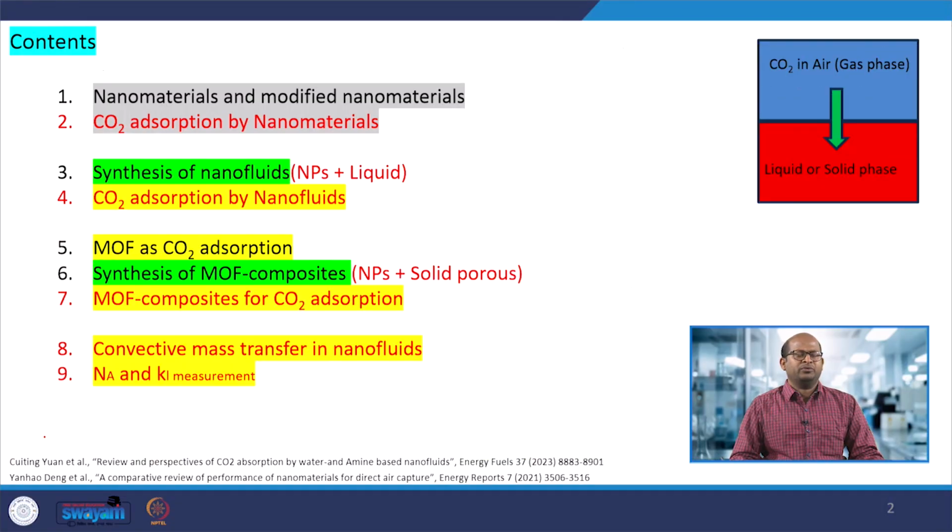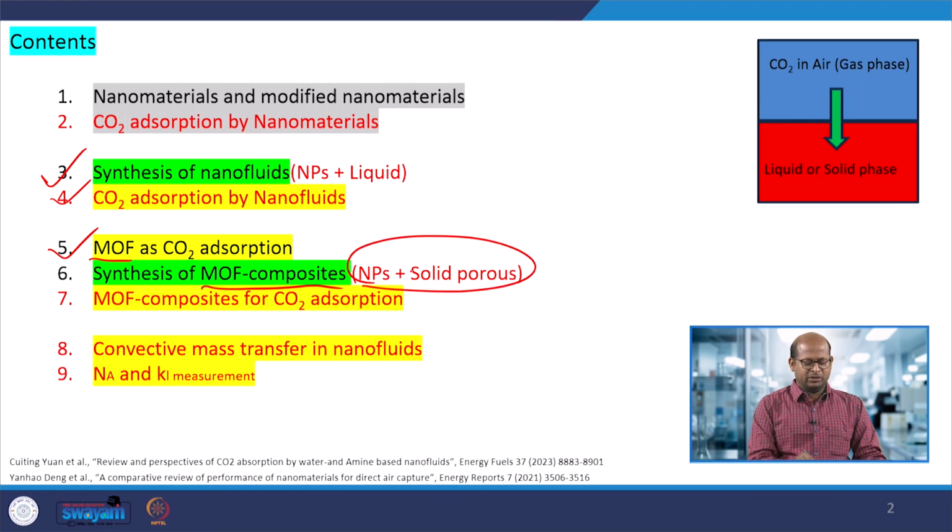So, here, the synthesis of nanofluids, which consist of nanomaterials or nanoparticles and a base fluid or liquid. How can nanofluids be synthesized, and what are the various methods available? Based on that we will discuss, and then CO2 adsorption by nanofluids, and then MOF, metal organic frameworks, which are mesoporous materials. That will be for CO2 adsorption study, and how MOF can be composited with nanomaterials or nanoparticles. That will be discussed, and then MOF composites will be used for CO2 adsorption.